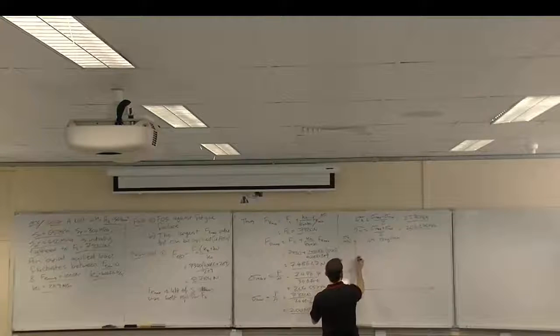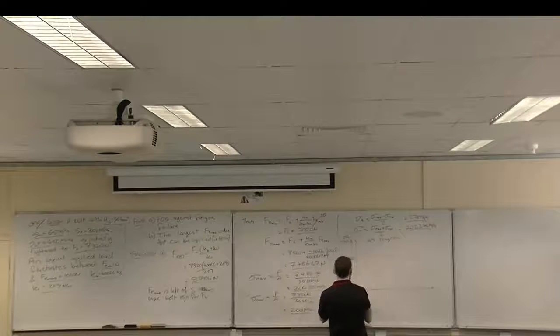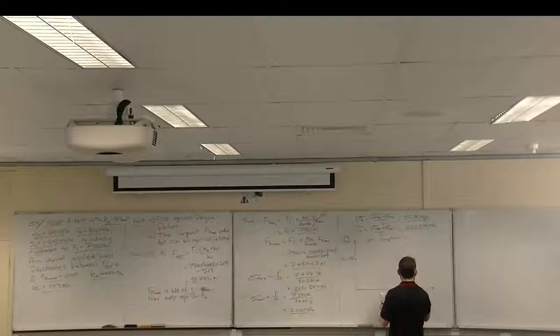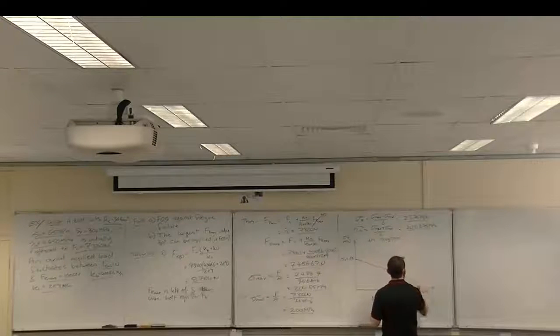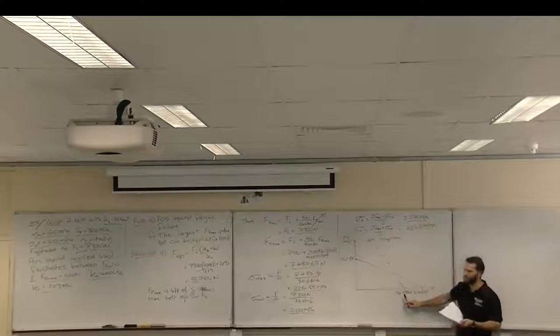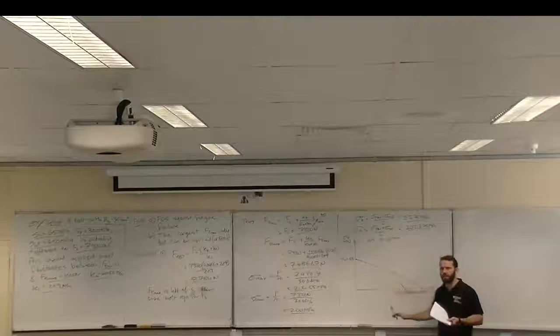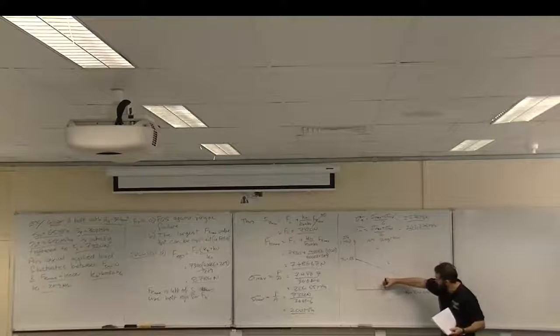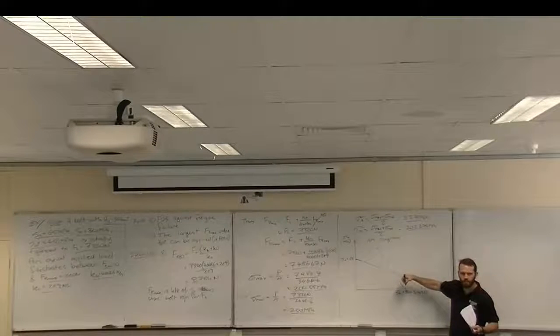Alright, so our S_N value is 65. We're using S_P here. And S_U is 450. Now, the value to use here, if you don't have bolts, I prefer that you use your proof load here. Remember that we said for static failure in bolts we use the proof load? The reason we previously had the yield line on an AM diagram is because the yield line deals with static failure. So if we carried along this line and hit yield, that's equivalent to our static failure criterion equation.